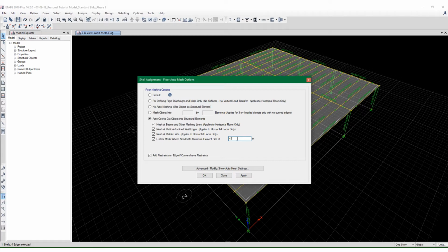There's something interesting that happens with ETABS. This setting is related to another setting, and I'll show it to you in a little bit. But basically, if this value right here was really small, and you had the membrane type that we have with such a small thickness to it, we get enormous deflections.